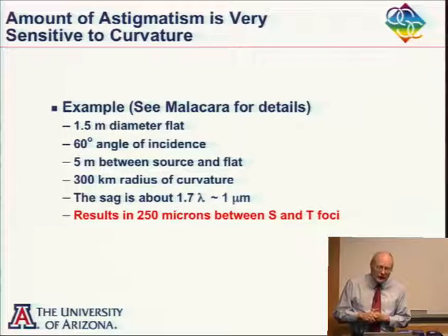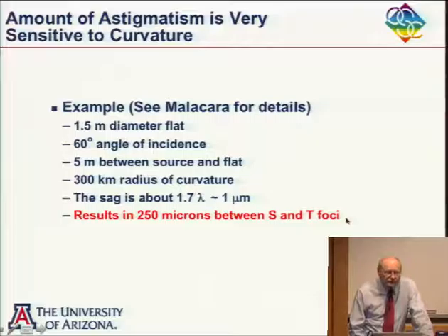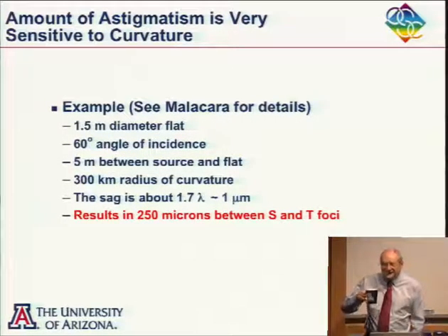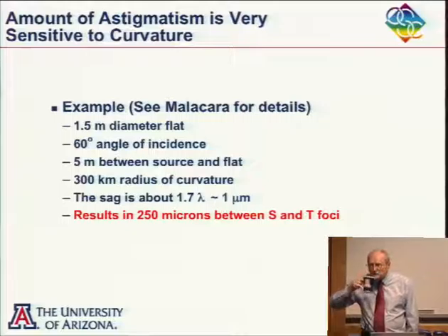Well, I'll ask you before I go on to the next slide. How might I tell whether it has astigmatism or just curvature? Rotate the flat, very good. Yeah, rotate the flat and repeat the measurement.